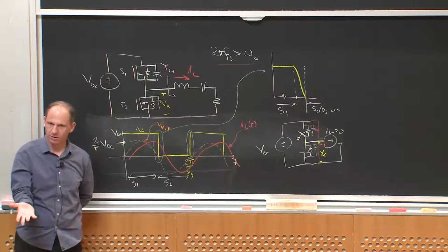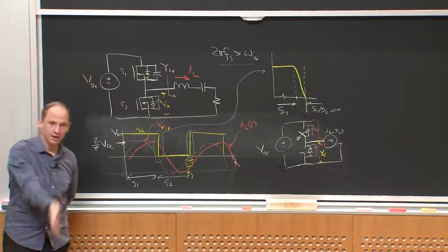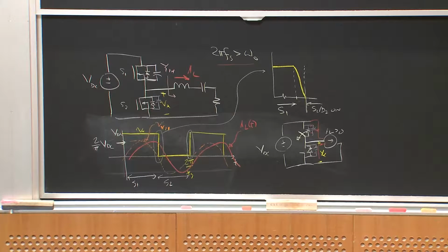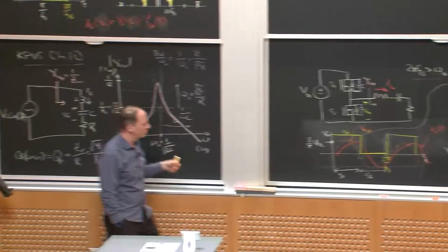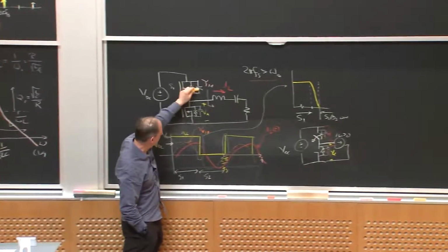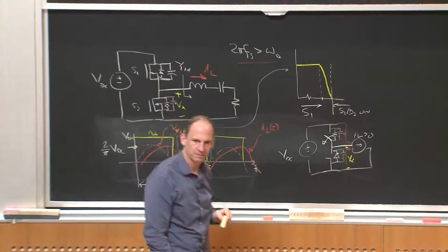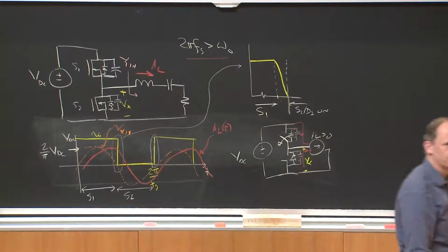So in most modern series resonant converters, because we're interested in 0 voltage switching, we will operate them up in this range above resonance by some degree and modulate power over this range by going down the curve this way. Now it turns out if I wanted to go the other way, I could actually do 0 current switching. If I operate below resonance, I could do 0 current switching. But we're often not interested in that, because with 0 voltage switching I can get rid of losses associated with the device capacitor switching. Okay? Questions about that?